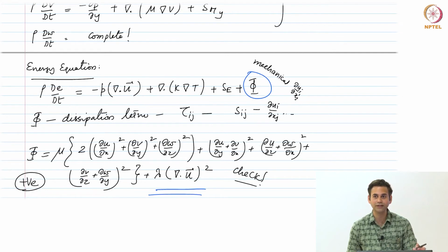It is creating the internal energy or temperature; essentially it is increasing the internal energy of the system. So, the dissipation term always tries to increase the internal energy of the fluid by extracting the energy from the mechanical component of the fluid, okay. So, that is responsible for the change in internal energy by converting the mechanical energy into the thermal energy. So, that is the only link, okay, fine.